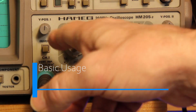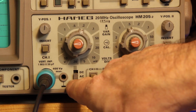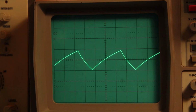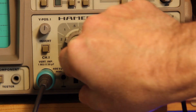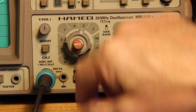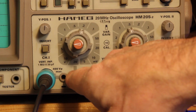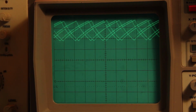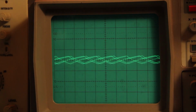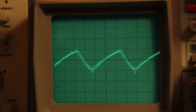At the input we have the Y positioning control, the phase inversion, and the coupling switch that has the GND position, useful to place the trace at 0, and the AC coupling, useful to read the AC component only in the case of an AC signal overlapped to a DC component, and the DC coupling position that provides the true signal. Finally, the attenuator allows us to select the proper amplitude, and its adjustable knob gives finer control.